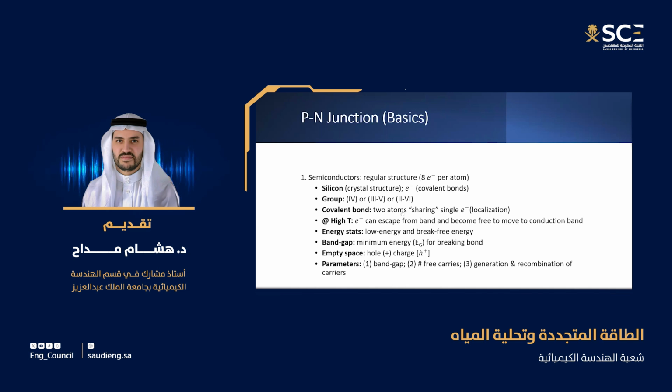You have covalent bonds. This allows the release of one electron, which can escape and go from one band to another. When you talk about the valence band and conduction band, we'll talk about this later on. Usually, when electrons take energy from the sunlight, they go from a low energy state to a higher energy state, and they escape from one side of the junction to the other. In the p-n junction, we'll talk about how the electron leaves an empty space. It's called a hole. When you have an electron, it's called an electron, E-. When you have no electron, it's called a hole, and this allows you to have free carriers. Free carriers means electrons and holes that allow you to have current generation from the system.